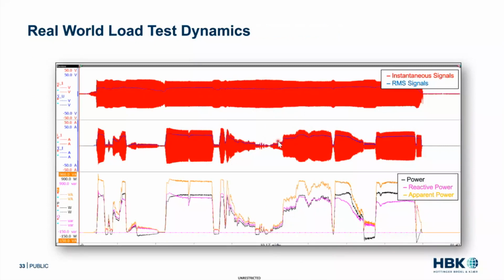And once you do something like a cycle detect, you can track fundamental frequency throughout a drive cycle. And you can actually look at the energy consumption, the power consumption throughout something like a WLTP or a WLTC cycle, and actually accurately trust your measurements during starts, during stops. You can evaluate when your power is overshooting. You can evaluate how your controller handles events like hitting bumps. So there's a lot you can learn from doing drive cycle testing, and you can account for those losses in the dynamics.